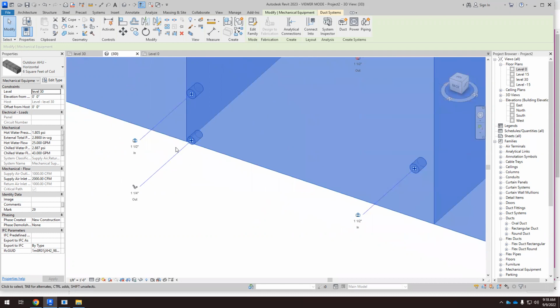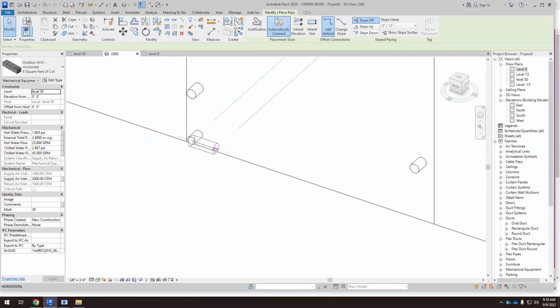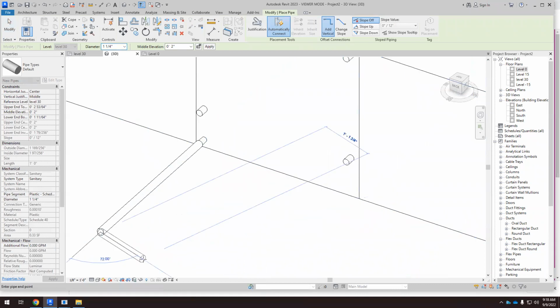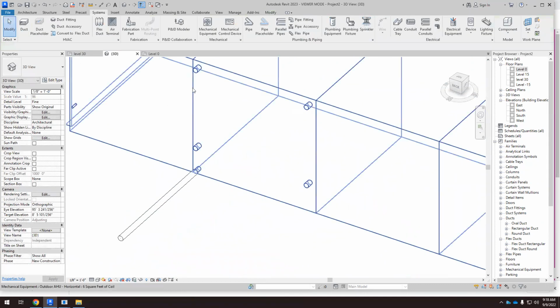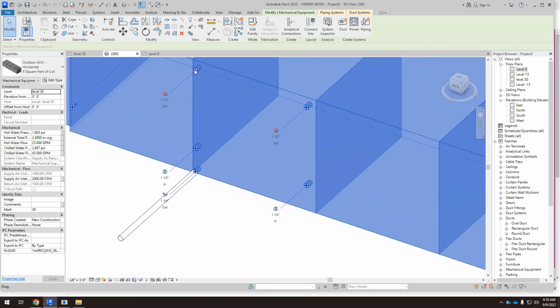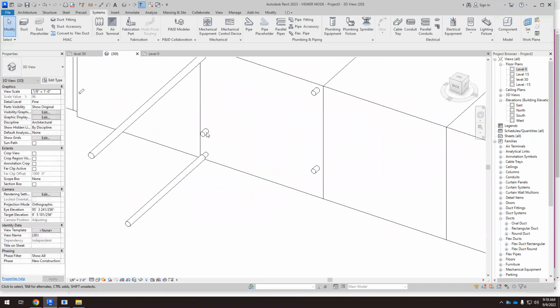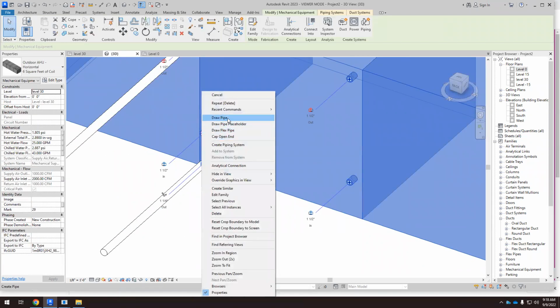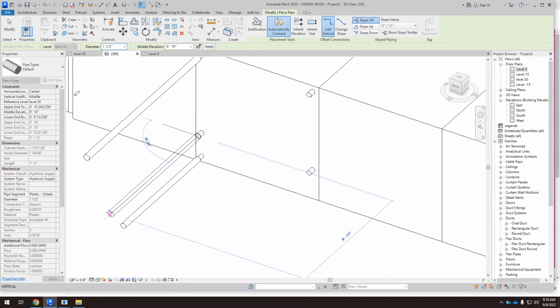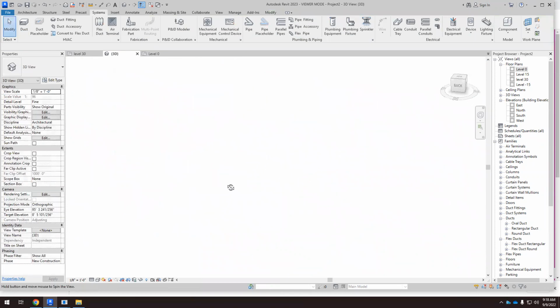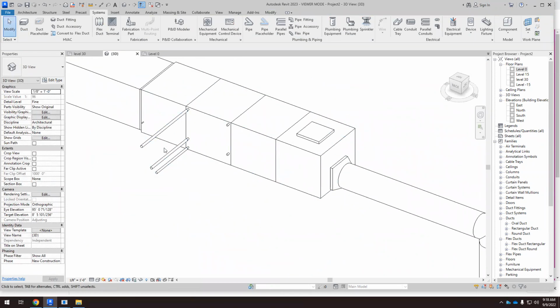So when we have a drainage, we can draw pipe. This is the drainage, and we have to connect this to the drainage system, and that's the cooling coil. So there's an outlet, draw pipe, and there's an inlet, draw pipes. That's the cooling coil, and then we need to connect this to the cooling system. So there will be something that cools water, and this is the heating coil, and we have to connect this to the heating system, so something that heats water.